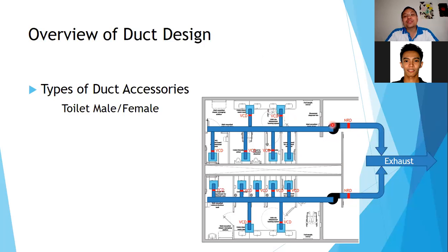So for example, this is your fan. It allows the fan to blow air from here going this way. But sometimes this toilet is turned off, or nobody's using this toilet, especially at nighttime. So this toilet, there's no more employee, and some employee went to this toilet and turned on the fan. So this fan will blow air, and this damper will prevent the flow of air from this side going to the other side. So the fumes or the odor from here will not travel from here going to the other side. So that's the purpose of your non-return dampers.